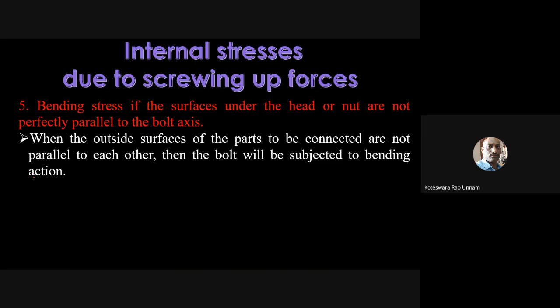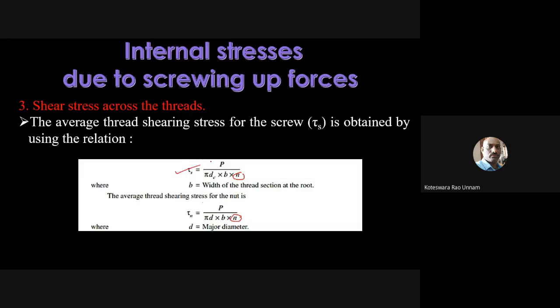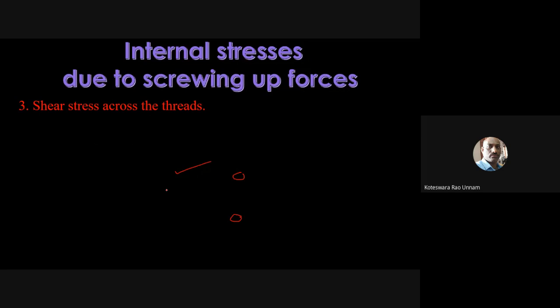Then if I go to the fourth one, here the projected area gives the magnitude of the crushing stress, which I can calculate using this formula. Then coming to the third one, here you can calculate the shear stress across the threads and also the torsional shear stress.